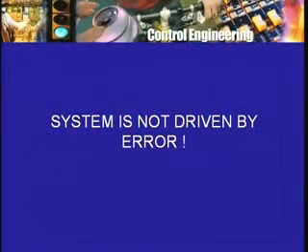In such a case, that signal E should not be called the error signal if by error we understand that the actual value of the output is not equal to the desired value. Something has gone wrong somewhere. The system is in error. No, that's not the case. This signal does not represent or indicate error at all. However, it does indicate something, and it is required to produce the desired speed.